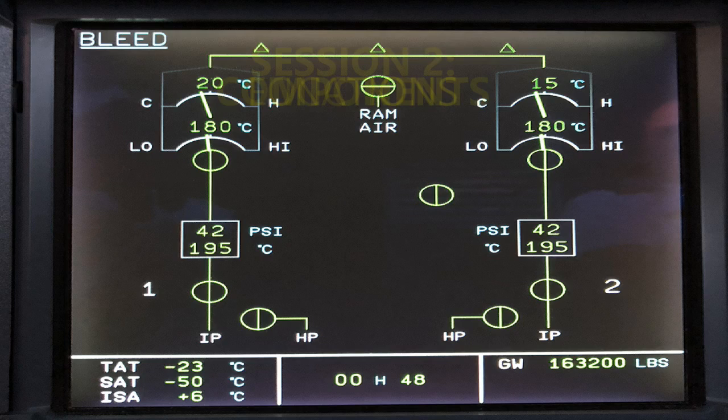But that's what its primary job is. It's just to cool that really hot air coming through. And since I'm getting ahead a little bit, you can just know that the key temperature there is 392 degrees Fahrenheit or 200 degrees Celsius. It's trying to monitor to keep it at a certain temperature and not be too hot. And basically the Precooler exchanger is a box. You've got an outlet flange, you have the inlet and outlet, the inlet box, which is where the hot air goes in, and then the cooling air from the fan. Okay, and you can kind of see that broken out.